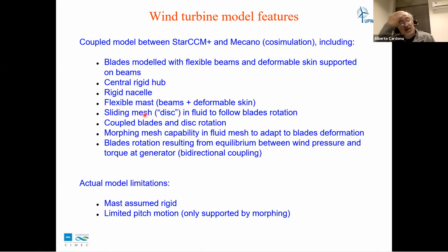And there are particular aspects of the simulation for taking into account the motion. We needed to use a sliding mesh capability in the fluid mesh in order to follow the blades' rotation, the rotation of the rotor. So this sliding mesh is rotating, and this rotation is coupled with the rotation of the rotor